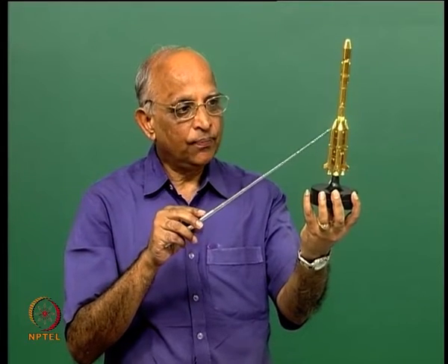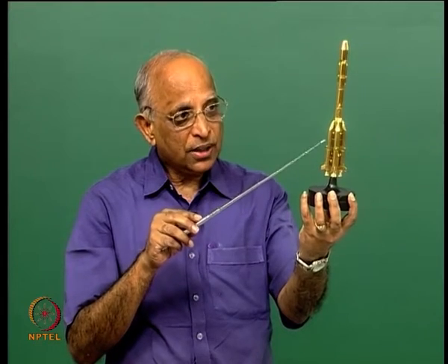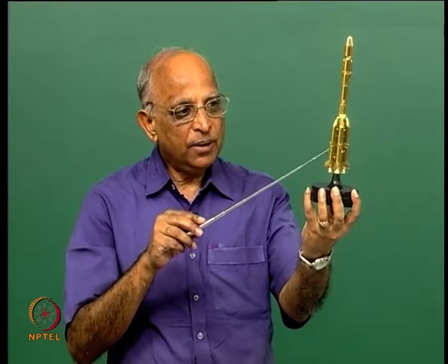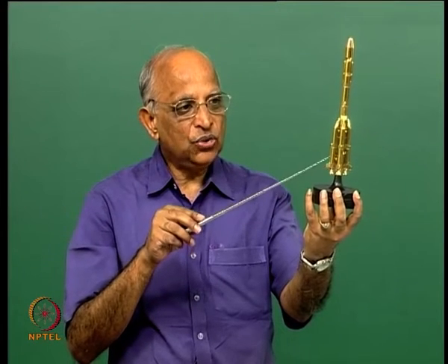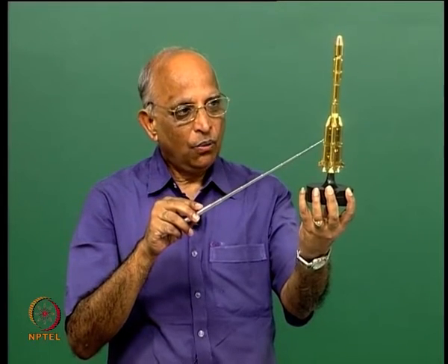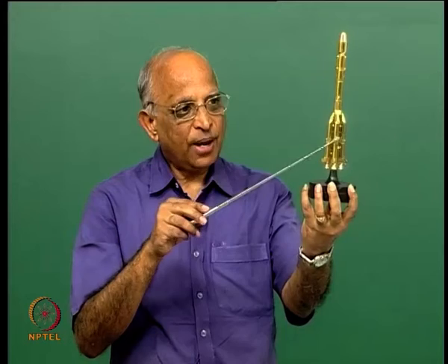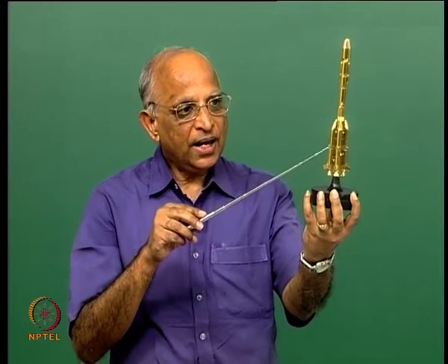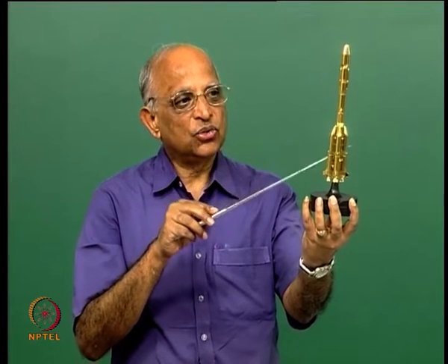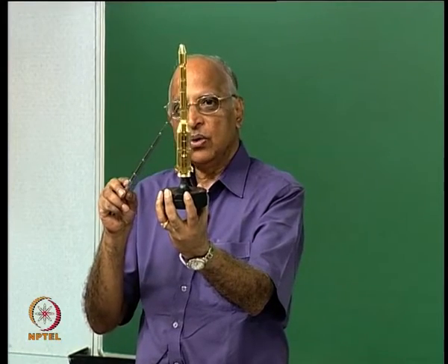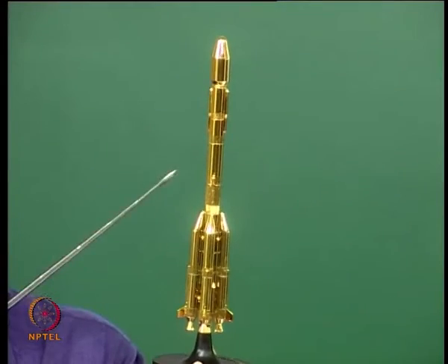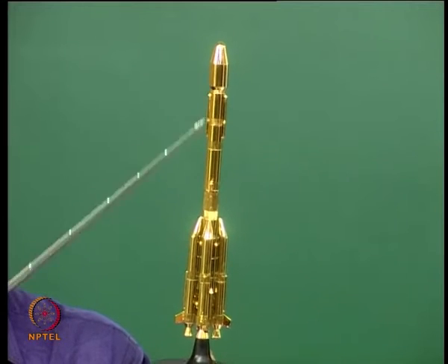At the beginning of the mission, the core or rather the straps either fire together or the straps fire before and immediately the core fires, so that you get a huge thrust which can carry the entire mass of the launch vehicle. Once the firing of the straps is over, they are discarded and thereafter the core fires for a small additional time and then this is also removed. Thereafter the vehicle goes up, the second stage fires and once the second stage operation is over, it is also removed and it is thrown out and then the third stage takes over.